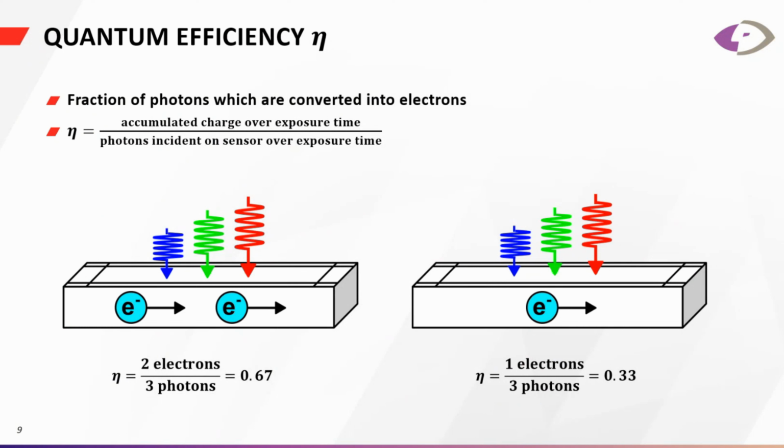Sure. So what happens fundamentally is light strikes the CMOS sensor. So it strikes the piece of silicon or whatever the material is, and it excites an electron to be conductive, meaning it can move around freely. And the idea in the camera is that you steer that electron into the well, and then it's measured by your circuitry.